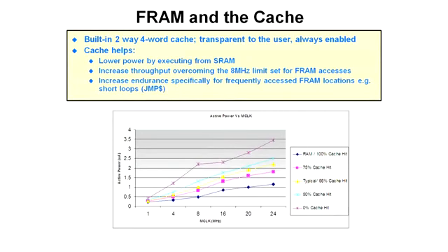So that's the active power in microamps versus the M clock in megahertz down there, going all the way down to a full-on RAM 100% cache hit down at the bottom. A typical would be right there about the center, the 66% cache hit. You can see it's still significantly lower in power per megahertz than if you didn't have a cache.